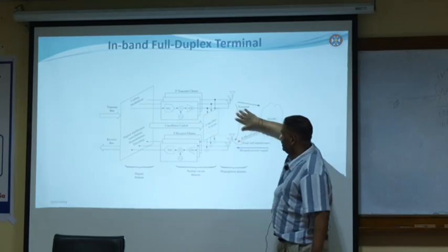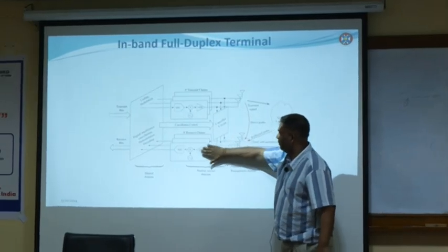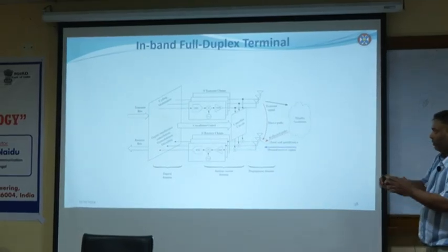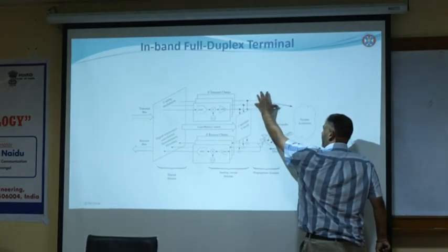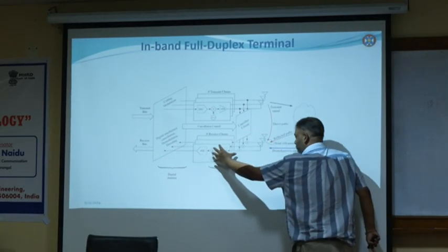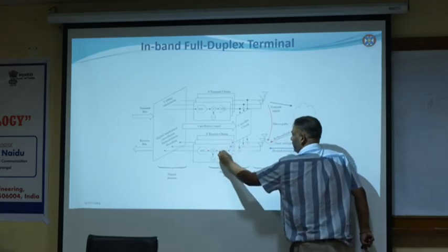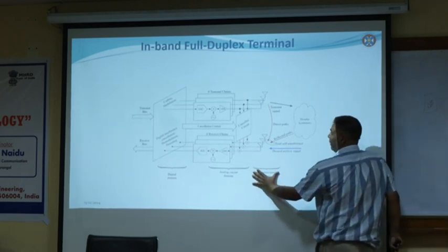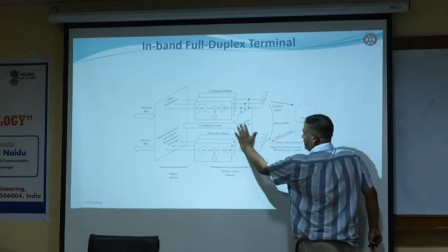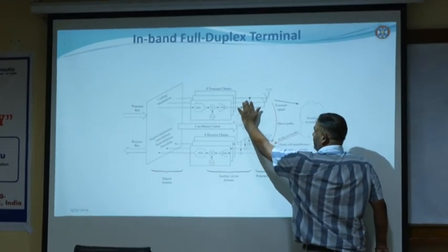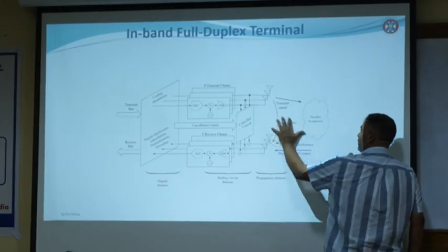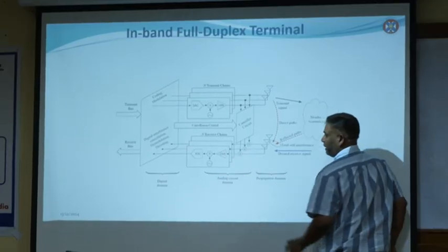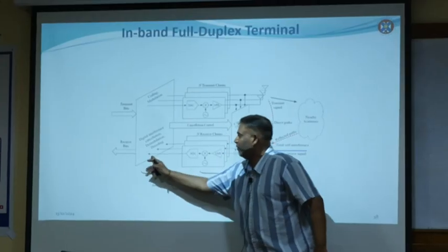If we don't do this self-interference cancellation, the receiver will be saturated because it's a strong signal, and then you cannot do anything. So we need to cancel in the propagation or antenna domain, and in the analog domain, so that the strong self-interference is not going to saturate this receiver. For analog circuit cancellation, you take the signal here, mimic the self-interference channel, and subtract before analog-to-digital conversion. And then the remaining part will be dealt with in the digital domain.